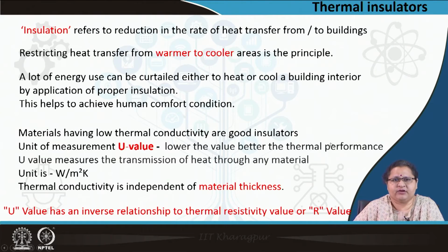Materials having low thermal conductivity will obviously be good insulators. You cannot have non-conductive materials. So, we will have low thermal conductivity, that means the U value of the material will be low and the thermal performance will be better, as an insulator it will be better.